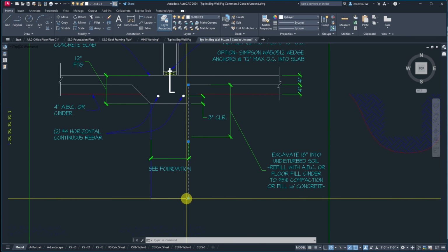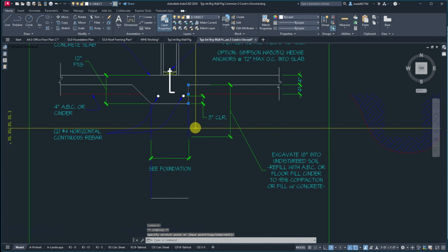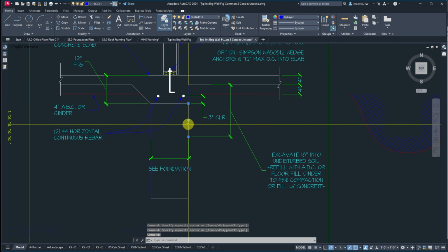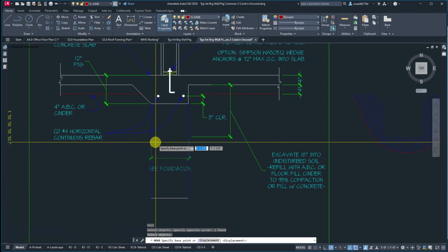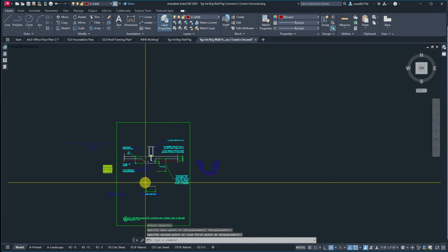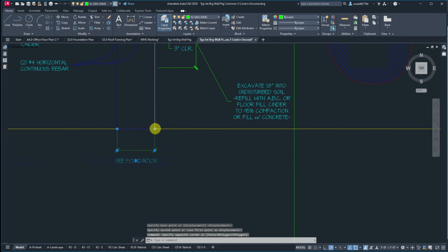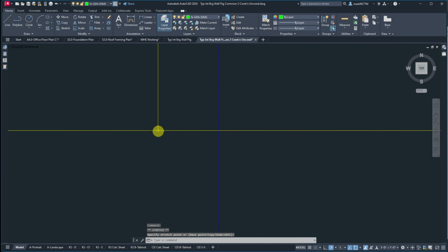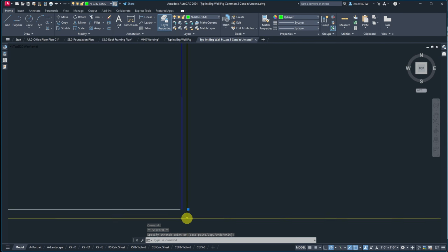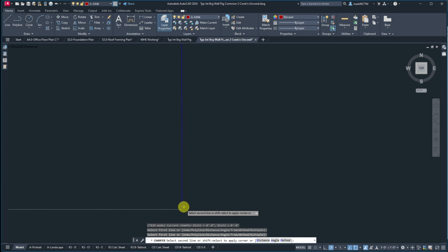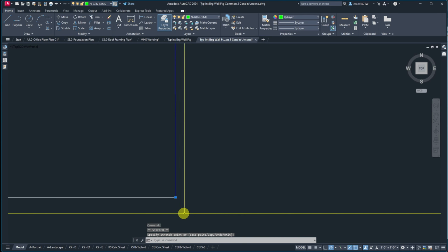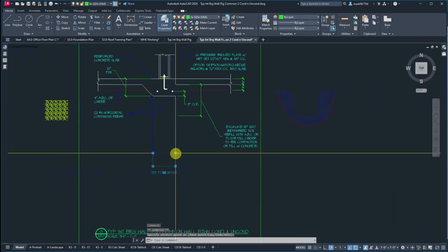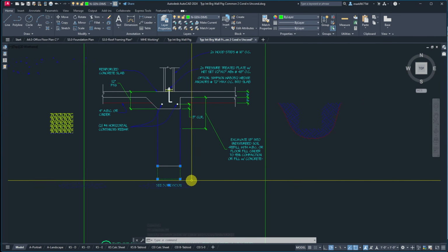Let's take my long one, shrink it up. Now I got my blue one, and I can bring it down. That was fast. And then let's move this from here to here. Let's re-snap it to there. Oop, missed. Didn't get it. Oh, and I don't have this chamfered either. Let's chamfer that first to make sure we grab the right one. Although it won't associate because I didn't create the dimension. So it's not like that just all of a sudden associated to it. So I move it again. I've got to move it manually.